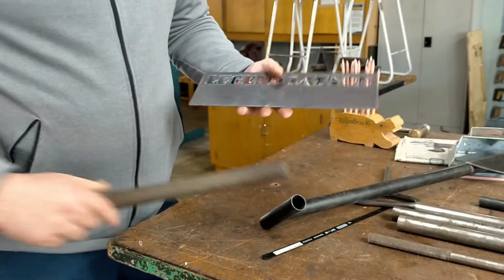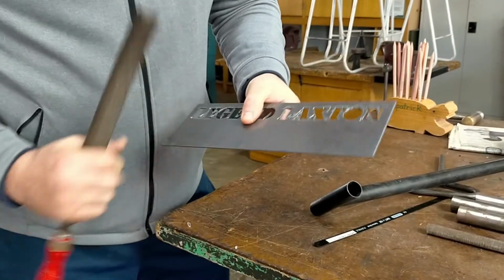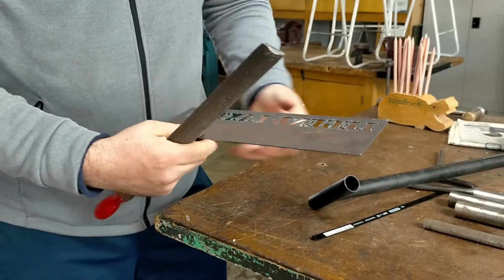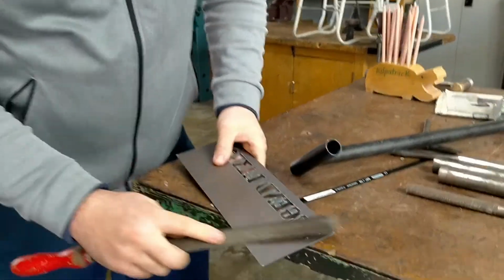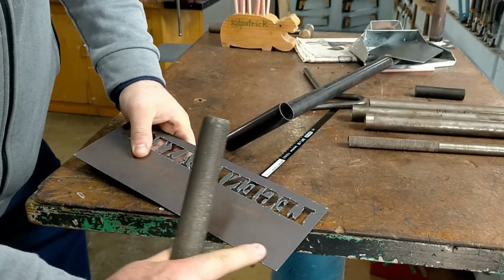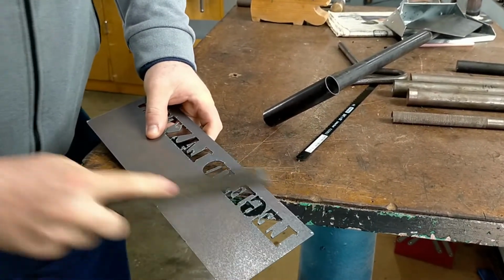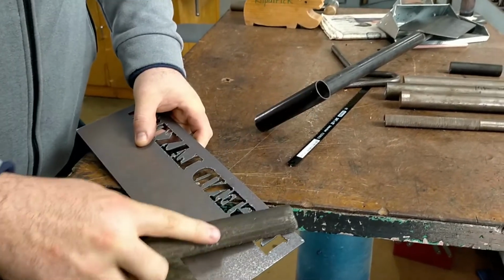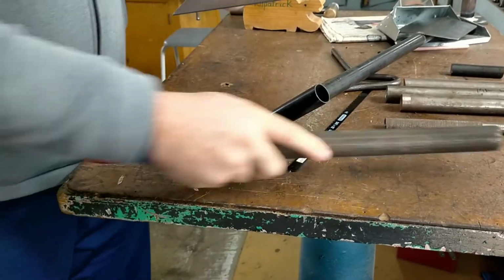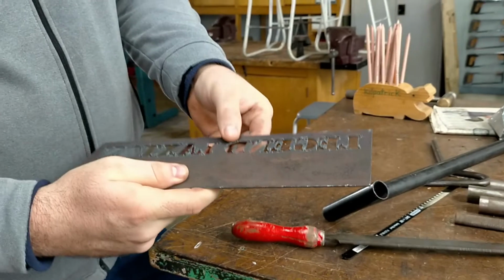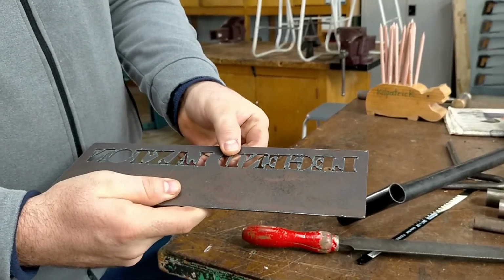But right now, just going around, clearing out. You see how easy that slag comes off? That's all part of actually getting the speed right. See, on the edge there, it all comes off really quickly, and in here as well. So I could go through and take all those off, but I'm probably going to do another one just because I'm not too happy with these.